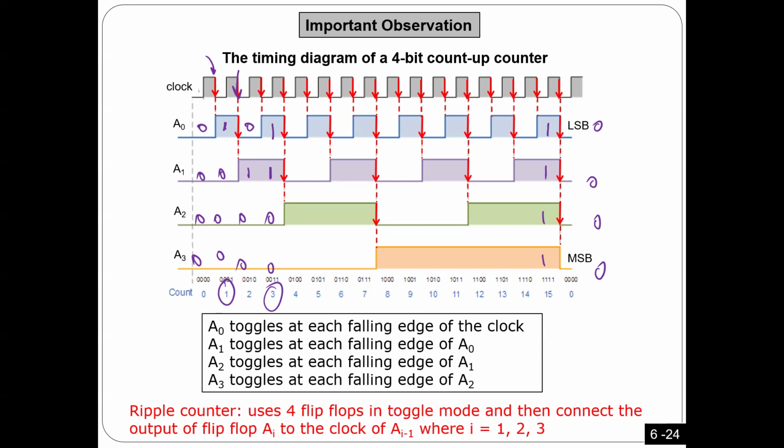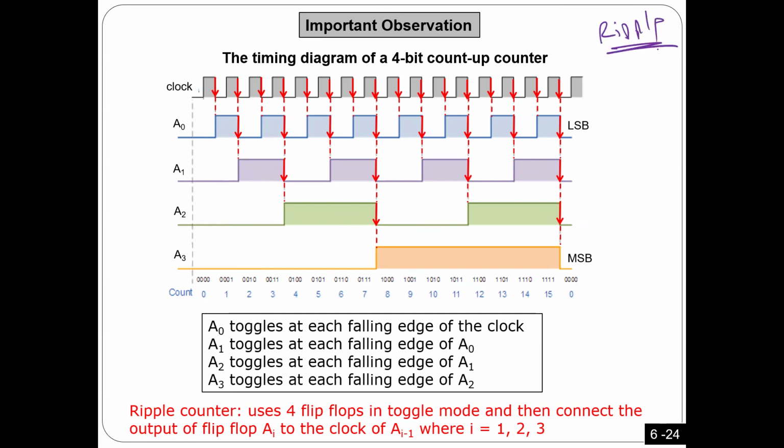Let's see how I can wire the flip-flops. That's why I'm telling you it's interesting. It's easy, it's not difficult. Look here, guys. What kind of observation are you going to have here? Number 1, these are 4 flip-flops: A0, A1, A2, A3. Let's look at one by one. Here, remember, I'm doing the ripple. Ripple means the clock of one flip-flop should come from the previous one.